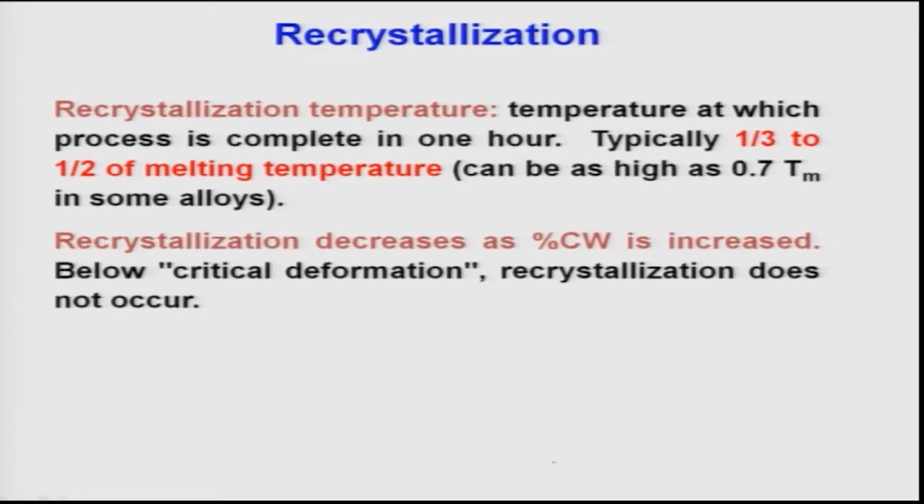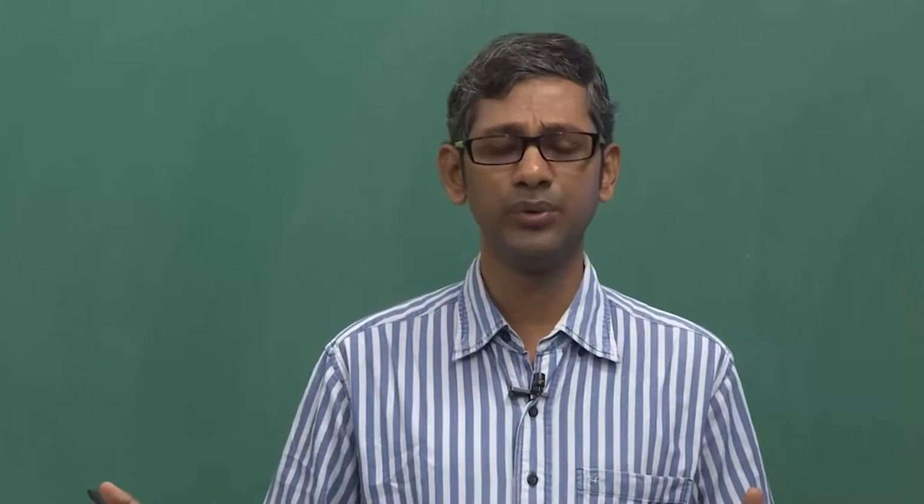And the recrystallization temperature normally decreases as a function of cold work. The more the cold work, the lower is the recrystallization temperature, because you have more strain energy, and the strain energy is the driving force for recrystallization. So below a critical deformation, recrystallization never happens. That is why if you deform a material by a lower amount of cold work, then only recovery happens, recrystallization does not happen, because you do not have the driving force left to form new crystals.